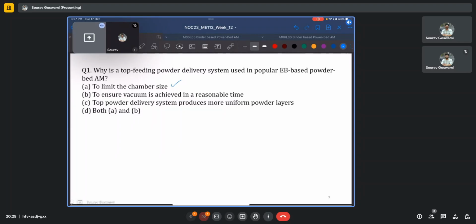This is the reason for the necessity of vacuum in the build chamber. A far higher degree of vacuum is also required in the gun chamber itself because there the filament is exposed to very high temperatures. The presence of any other particles can lead to oxidation, maybe even combustion, and thus the filament will fail prematurely with a very short life.